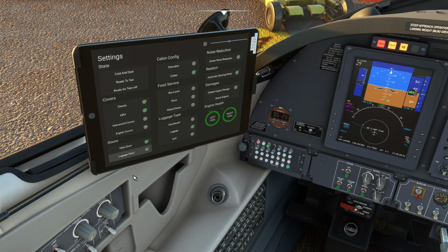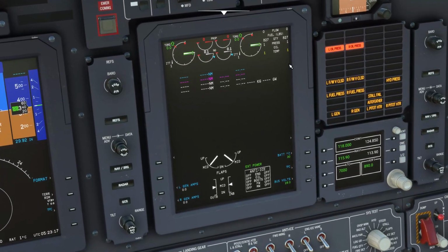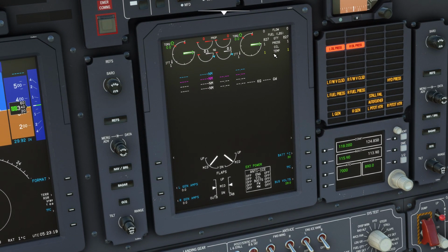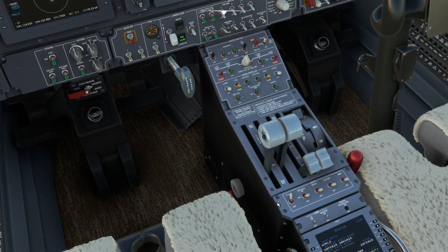So since everybody's on board, let's close the door. We can get the laptop. Chuck is still here, right? Fuel quantity is here. It is in pounds, unfortunately. So 827 pounds each side, which roughly gives us around 750 kilograms of fuel. Passenger signs, which are here. So, ladies and gentlemen, fasten seatbelts, please.